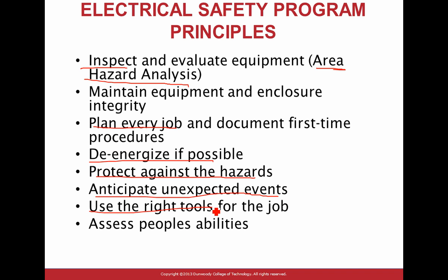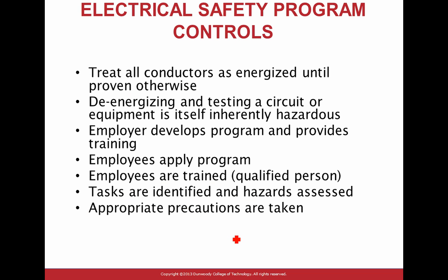And we talked about these, gentlemen, and assess the people's ability. As a manager, you have to assess, are they capable of doing this type of work, locking, tagging, working on this equipment or not? So that's a summary of every electrical safety program, typically part of your maintenance program. So that's the principles, the control. Now treat all conductors as energized until you de-energize them. De-energize and test all the circuits.